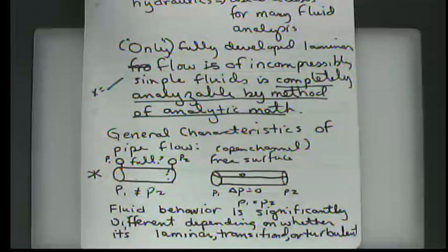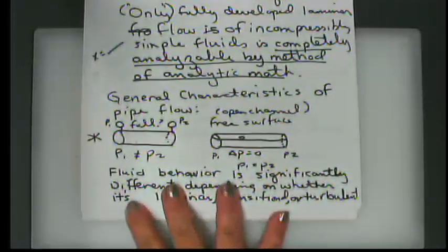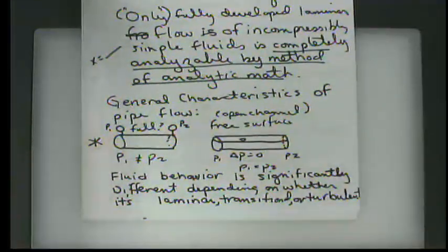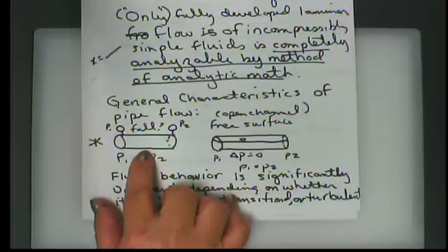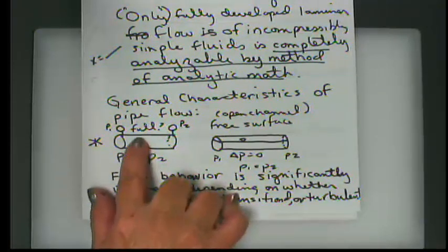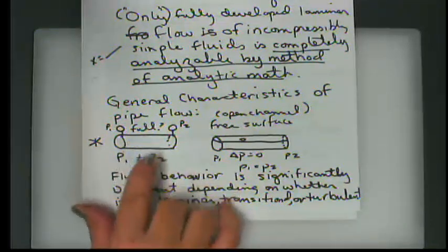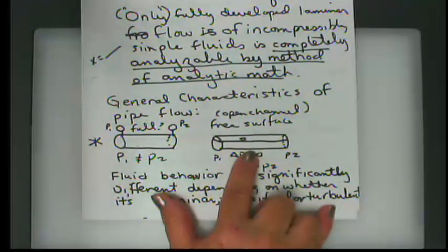So, talking about that, we divide it up all kinds of ways, because what we really try to do is to get to an idea of looking at a fluid flow regime in a way that we can eliminate the things that are no longer important to that flow. So one of the ways that we split flow up is, if we have fluid flow in a pipe, we divide it up into whether the pipe is flowing full, in other words, if the fluid is all the way up to the top and covering the entire circumference of the inside of the pipe, or if we have a free surface.